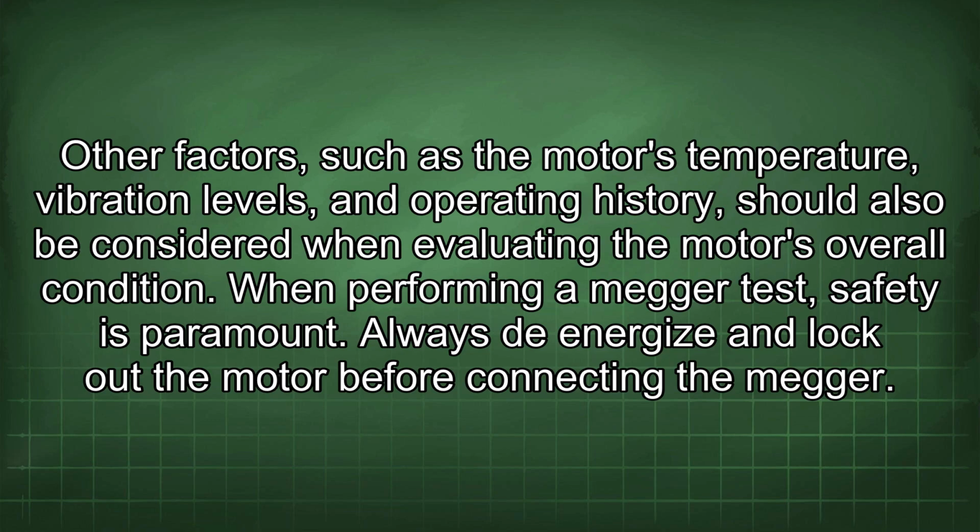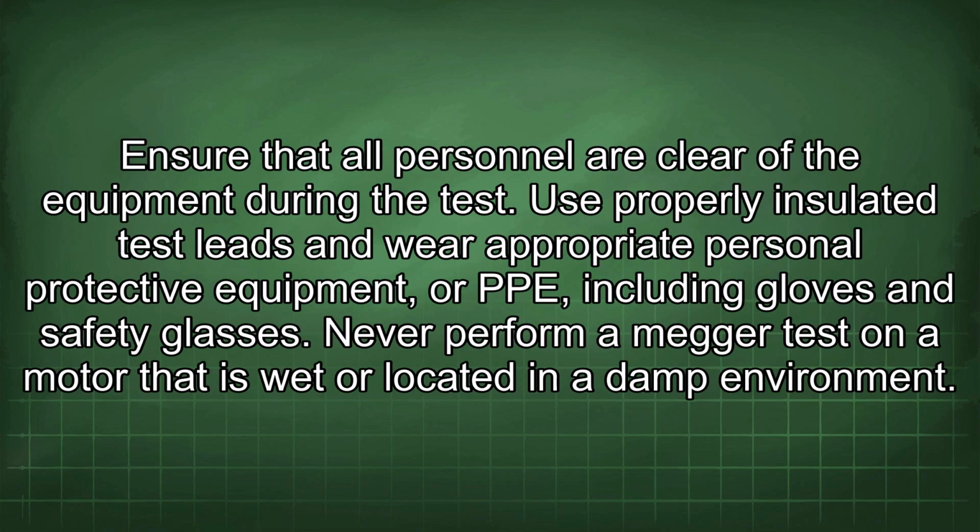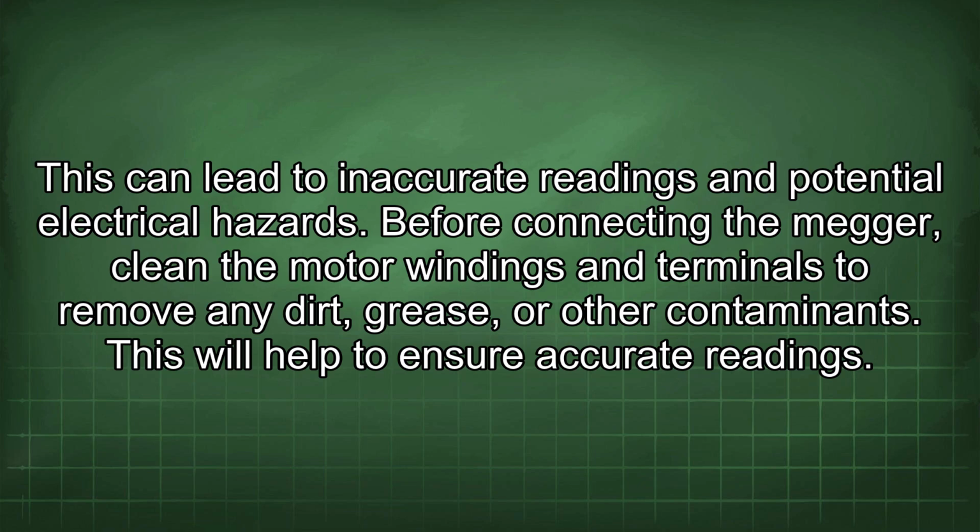Always de-energize and lock out the motor before connecting the Megger. Ensure that all personnel are clear of the equipment during the test. Use properly insulated test leads and wear appropriate personal protective equipment, or PPE, including gloves and safety glasses. Never perform a Megger test on a motor that is wet or located in a damp environment. This can lead to inaccurate readings and potential electrical hazards.